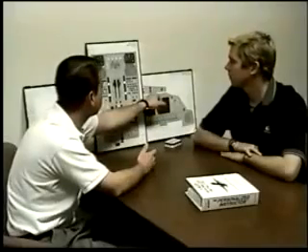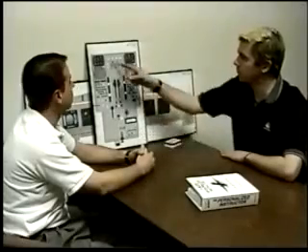Some of the master warning CRCs cannot be canceled with the master warning switch. You have to do it with an emergency cancel. The other part of the question is you get a level 2 single chime master caution, and instead of selecting the master caution to reset for the next ECAM, you select emergency cancel. What occurs now? Well, now you've suppressed the ECAM, and on the lower ECAM, on the status side, or on the inoperative system side, it'll give you a list of ECAMs that have been suppressed via the emergency cancel. And if that reoccurs on the flight, you won't be notified about it.